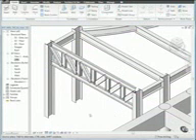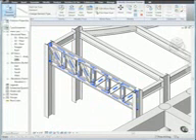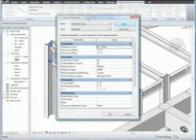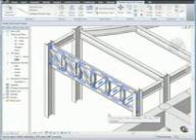Next, we will change the truss level offsets. Select the entire truss, not just the left vertical web or truss cord. Then, click the Element Properties drop-down and select Instance Properties. In the Instance Properties dialog, under Constraints, for Start Level Offset, type -3 feet 5 inches. Then, make the End Level Offset -3 feet 5 inches as well. Then click OK. This lowers the top level of the truss to the same level as the other beams in the entryway frame.